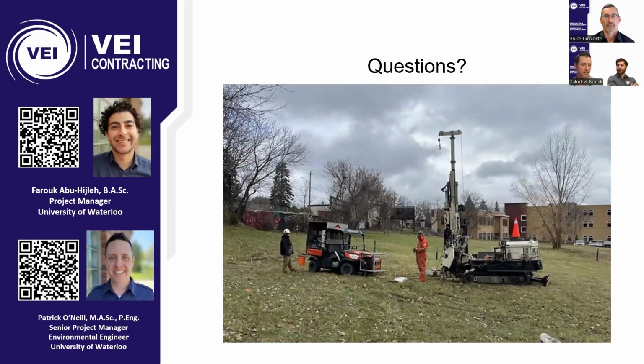Well, yeah, I want to comment on that because I want to make sure we're talking apples to apples. If you're talking about doing hydraulic connectivity assessment through slug tests, you still need to drill the wells. So that rig is still going to come on site. Yep. And then you need to go develop the wells. And then you need to actually do the slug test. And then you need to go analyze the data. And then you get your number, right?